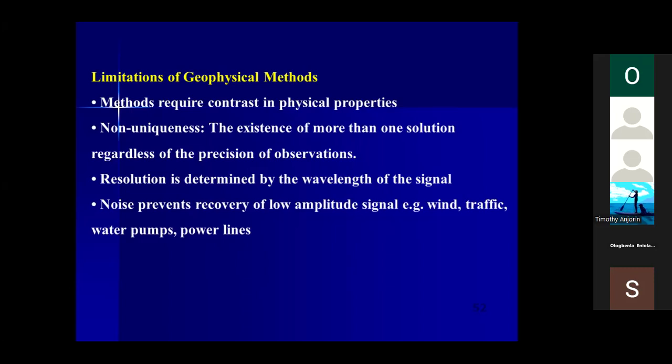And you have to set your objective. What is your target? Why are you going out on field for investigation? So you have to set your target. You have to know the geology of that environment. And your borehole data is also very important, which you use in validating your interpretation.